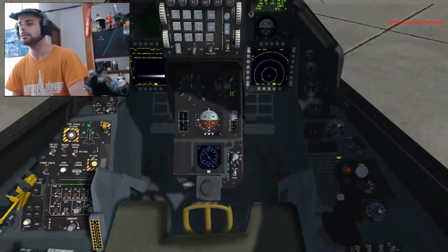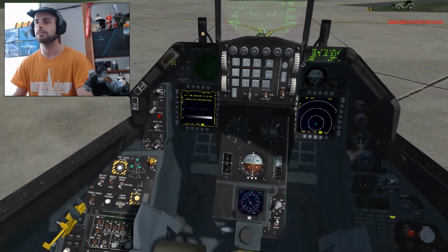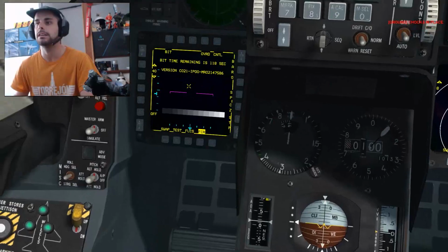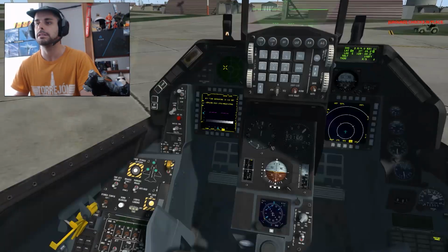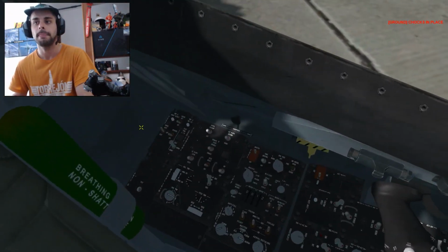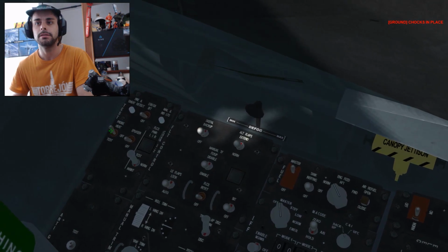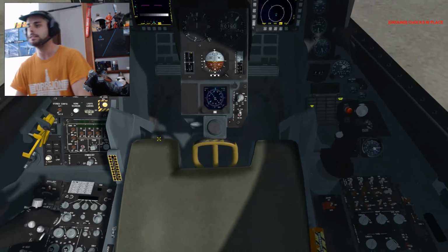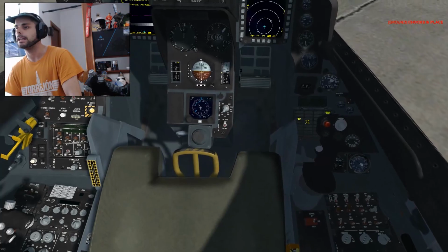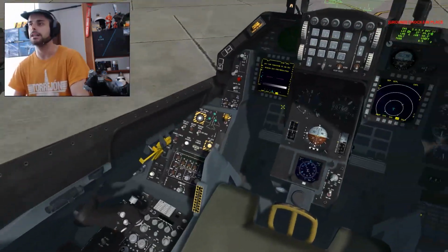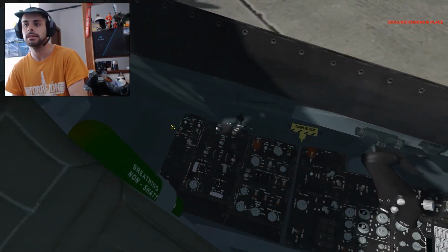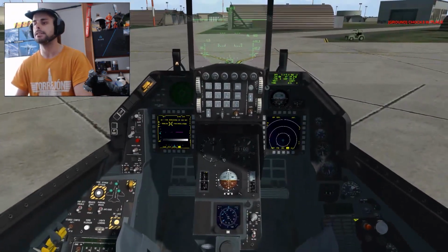Okay, now it's out the button. Okay, perfect. Master caution is off, and you can see here the radar auto test. More tests to do. Prof in the down position is test. As you can see, aligning, flashing there. Okay, and also the master caution. Turn off the test and reset the master caution.